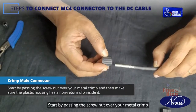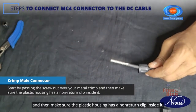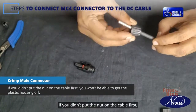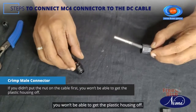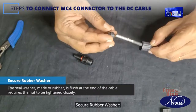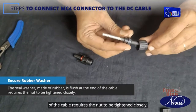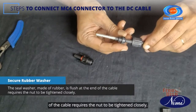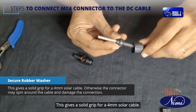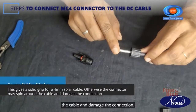Start by passing the screw nut over your metal crimp and then make sure the plastic housing has a non-return clip inside it. If you didn't put the nut on the cable first, you won't be able to get the plastic housing off. Secure rubber washer. The seal washer, made of rubber, is flush at the end of the cable, requires the nut to be tightened closely. This gives a solid grip for a 4 mm solar cable. Otherwise, the connector may spin around the cable and damage the connection.